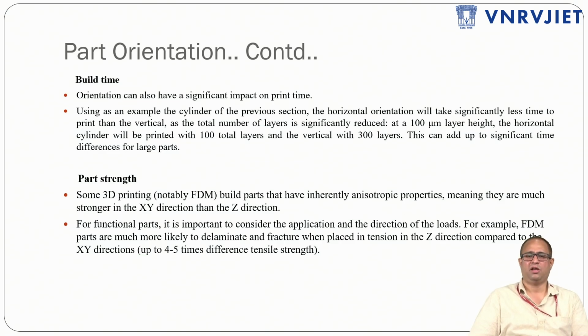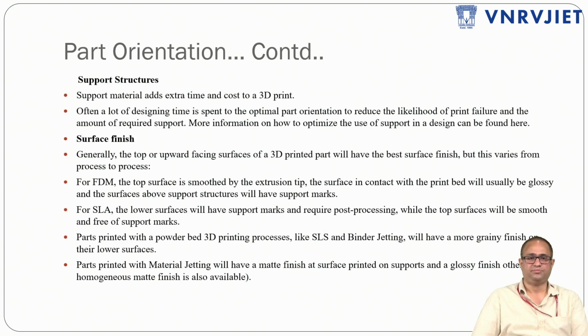If you take the case of fused deposition modeling, for functional parts, it is always important to consider the direction of the applied loads. So where are you going to apply the loads? For example, FDM parts are most likely to delaminate and fracture when placed in tension in the Z direction compared to XY. So you always need to see the direction of the loads, and based upon that we need to choose the orientation to print the parts.